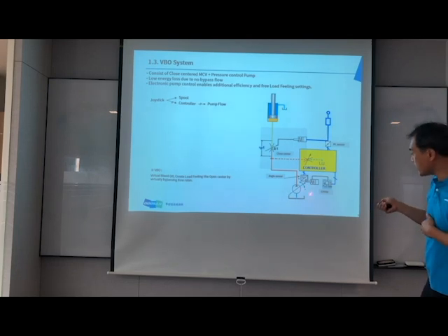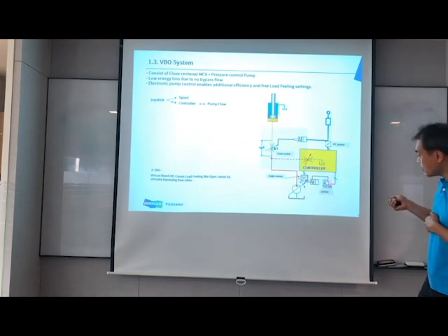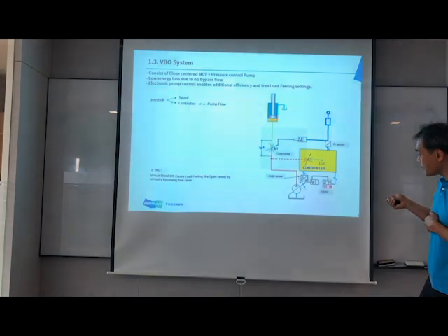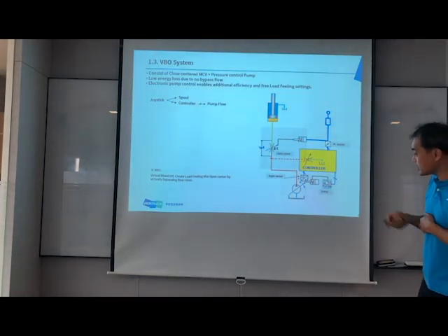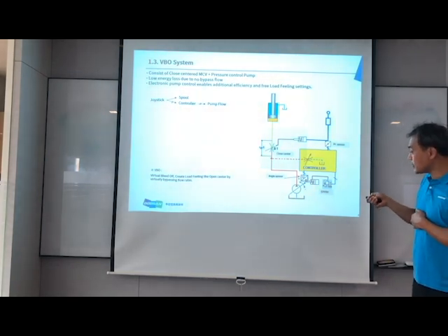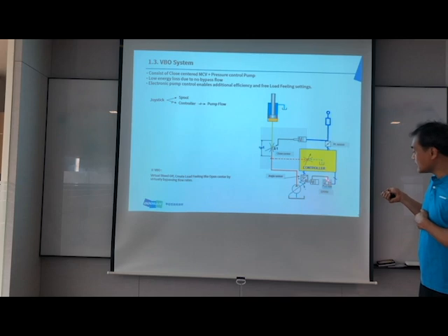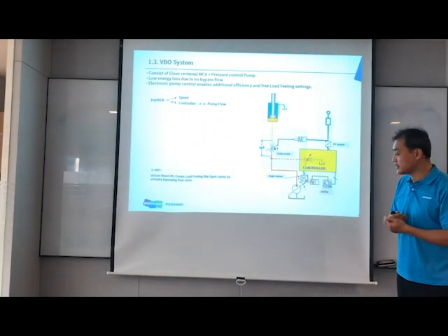But there is no physical hydraulic signal line to the main pump. Actually, the main pump has one EPPR valve. The EPPR valve gives the pilot signal to the main pump to increase or decrease the flow. Anyhow, the main pump takes the signal from the controller, FPOS, through the EPPR. Finally, the EPPR gives a signal to the main pump to increase or decrease. It is actually controlled electrically, with no physical pilot line.